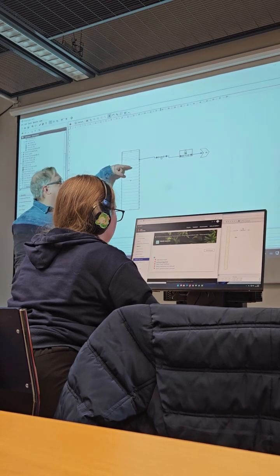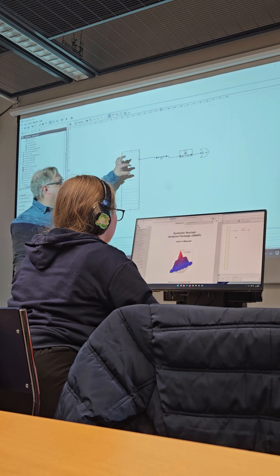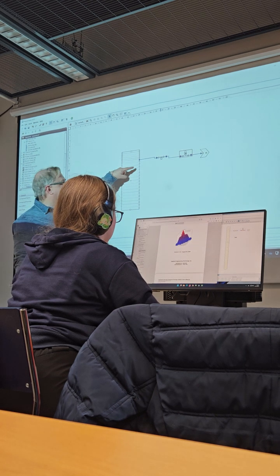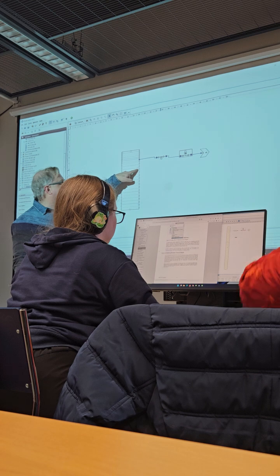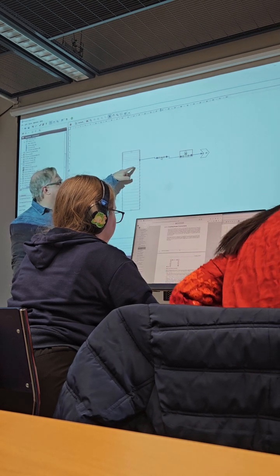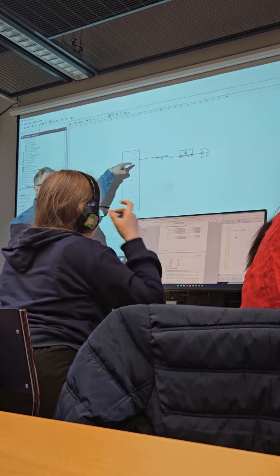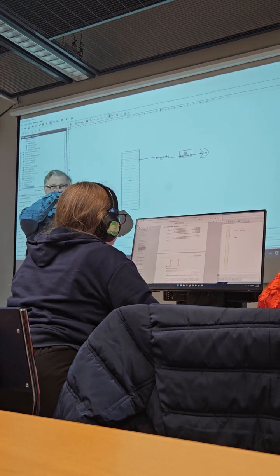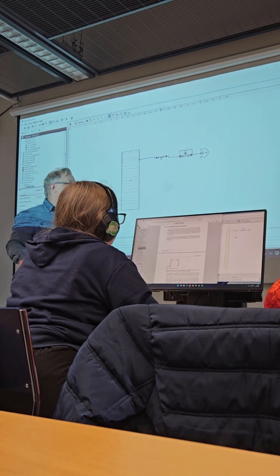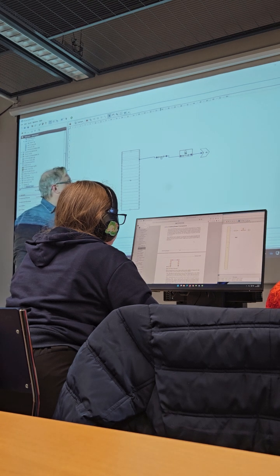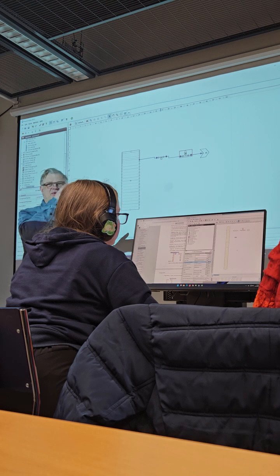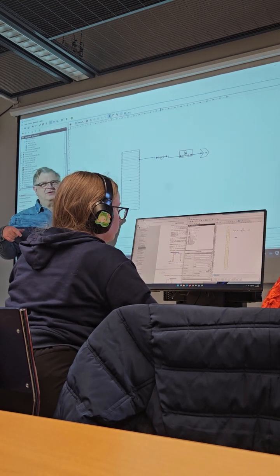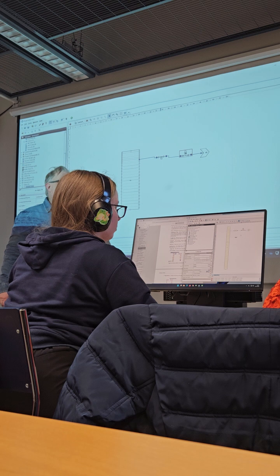And also, if you want to check the level, so that level is between some of these nodes. If this is covered, for instance, with water, then it's of course 0. And above it, it's 1. And you can assume that level is in the edge of those nodes, but of course, you can also assume that it's in the middle of one node, and then you put 0.5. So that's a very simple trick. It's the void fraction.